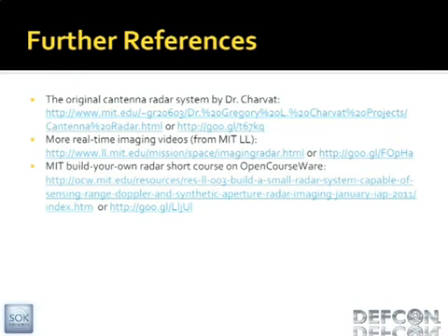But yeah, it's pretty open. You basically get different characteristics. If you're trying to do the SAR imaging, having a wide beam width is actually somewhat useful because it decreases some of your spatial fidelity, but you also get a wider image. If you have a very narrow beam, you're not going to get any signal from something that's further apart. So it's a trade-off there.